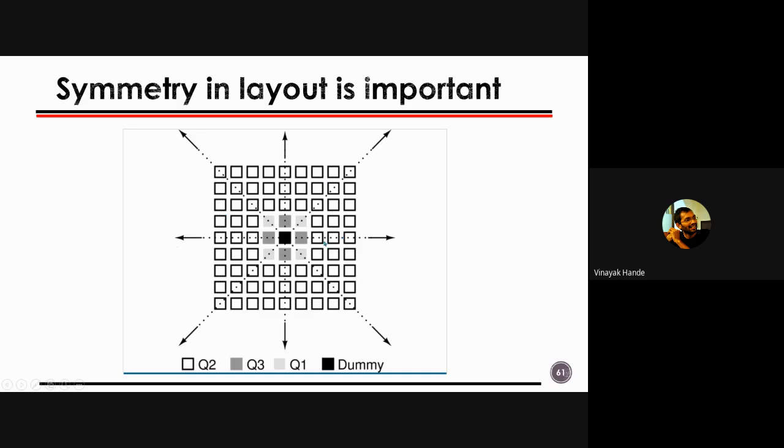So it is always good to have a wider transistor where n is an odd number, right? If it is not an odd number, then you have to put the extra dummies into that, but unnecessarily why waste the area? Better to have an odd number of n. And I think you know what I am talking about. N is that bigger transistor area I'm talking about, right?